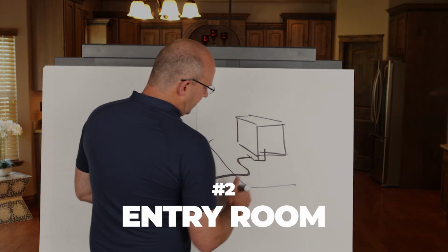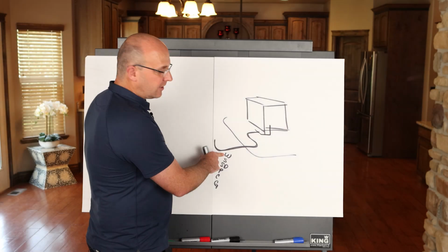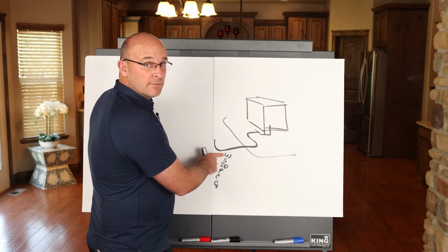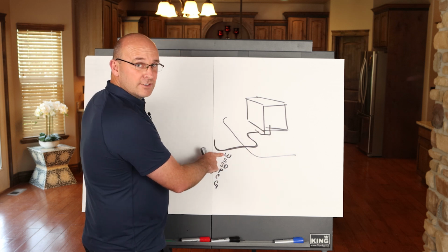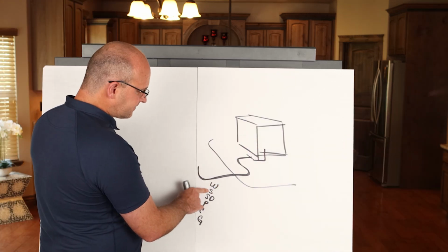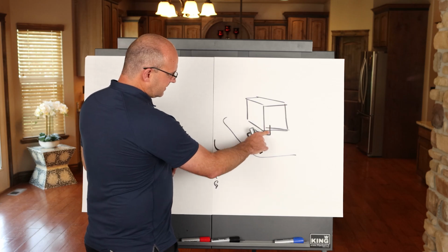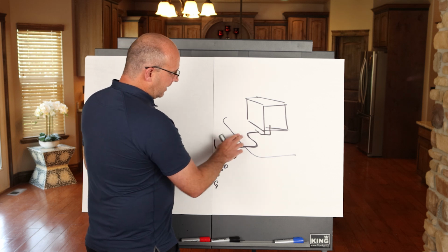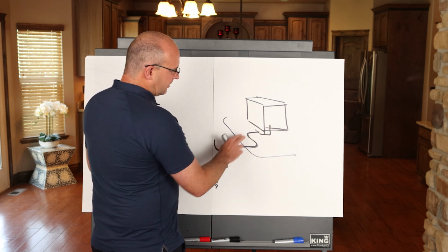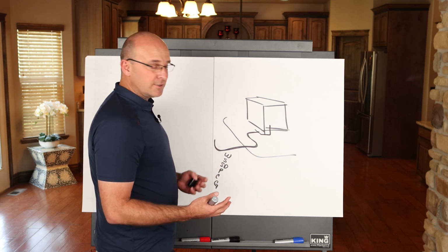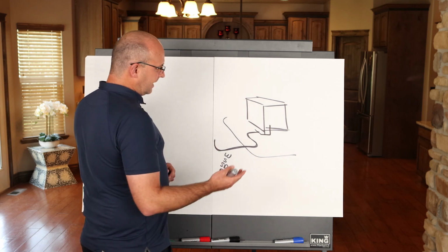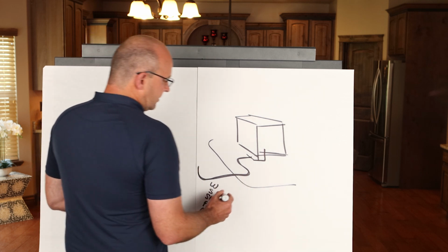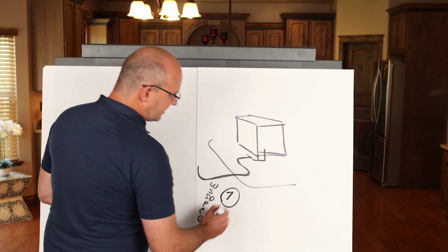So you're going to be taking these same things, right? Your water will come into your fire pump room. It will come into your mechanical room to feed your domestic water. It might even feed out to your irrigation. Your sewer, you're obviously going to connect to your sewer system. Storm drain, connect your storm drains. Power is going to come in through the service entry section. Communications is going to come in through your main distribution frame, your MDF, right? And gas could come up typically anywhere where it's safe and per the design, typically in the mechanical room. So this is like the first step, bringing the utilities to the building.